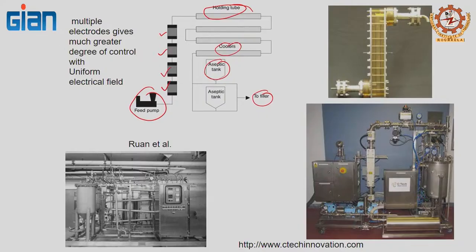Then you pass electric current through it, which warms up the material, say to 50 Celsius. At 50 Celsius, the electrical conductivity value may increase, maybe from 1.2 to 2. With that, it allows more passage of electricity, so you can increase the temperature much more rapidly.